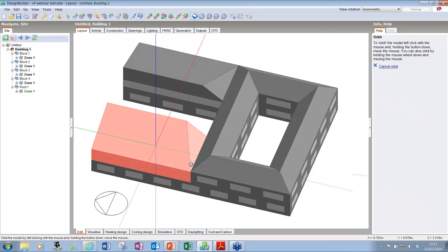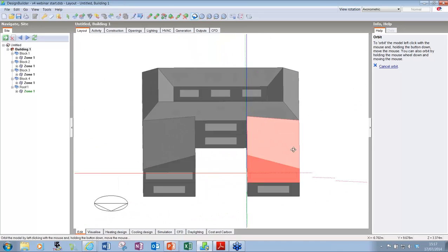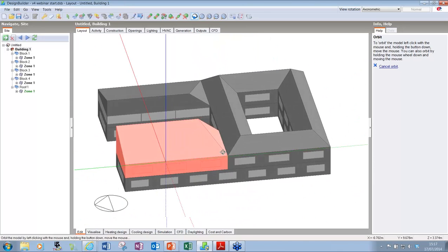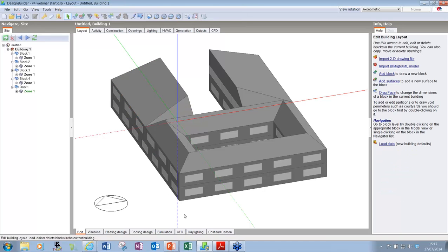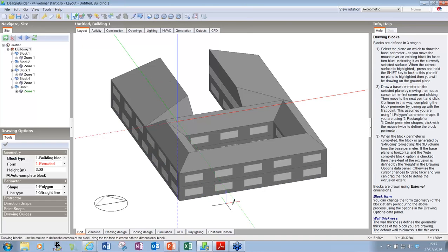The final geometry tool I want to show you is the Boolean operator, which now works completely reliably due to the modeler introduced with V4. Before I do that, I'll add an entrance to the north facade, which in this case I'll use the arc perimeter option.